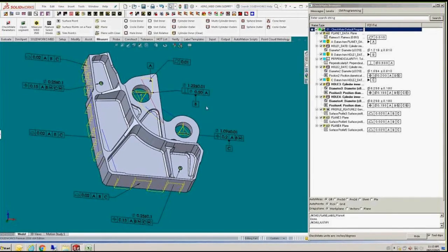We take the tolerances and the nominals from the CAD model, and we add CMM sensor things such as approach and retract, and how deep into the holes I have to go, and we put all that together and create these measurements in our programming browser automatically.